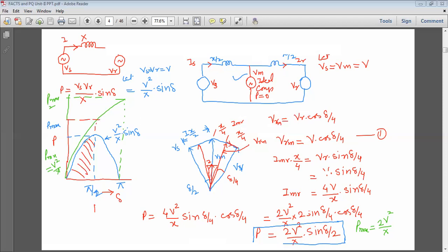So with the compensation, the steady state stability can be improved, as a large margin is available for the transient condition. So both the steady state stability and the transient stability can be improved. And second, the power transmittable ability of the system can be improved with the help of the midpoint compensator, isn't it?